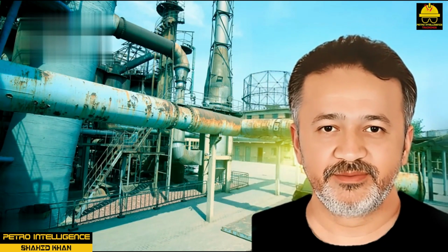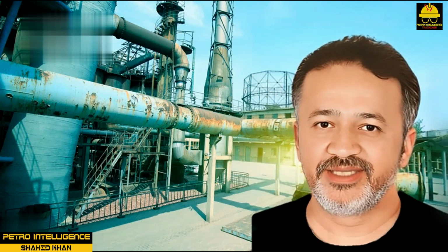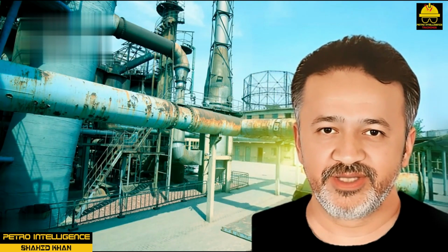Coagulation and flocculation. Coagulation neutralizes the negative charges of suspended solids, thereby allowing them to clump together and settle out. Flocculation is a term used to describe the bridging together of coagulated particles, that is, floc. Common coagulants include aluminum and iron salts. Chemical names for these coagulants include ferric sulfate, ferric chloride, aluminum sulfate or alum, and sodium aluminate. Aluminum and iron have 3 positive charges that counter the negative charges of the suspended solids. Coagulants form a floc net that collects suspended material.